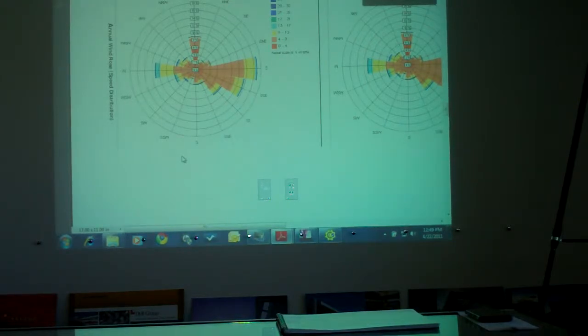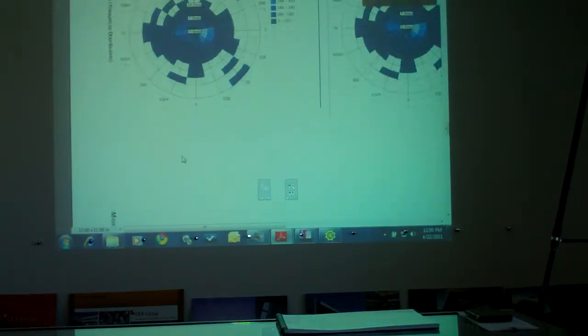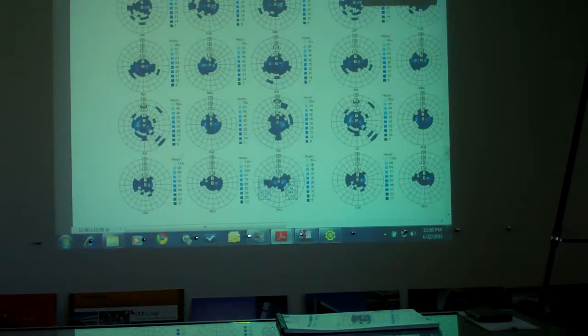It's like you said at first, it's best for determining this design shape versus this design. Correct. The same criteria. Right, and you just figure out, okay, this design is consuming 49 kBTUs per square foot per year. Option B is 42. So if the difference between option A and option B is 7 kBTUs per square foot, I cannot tell my owner that that's what I'm going to save. Still, as a design process, I would say it has a savings. It's a better design, so I'm going to go to option B, if you have both available. Right.